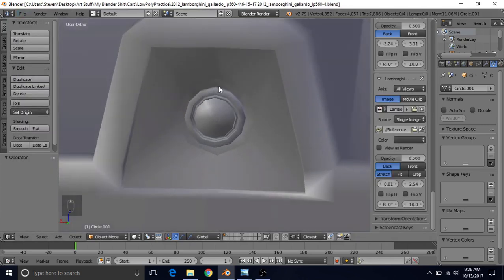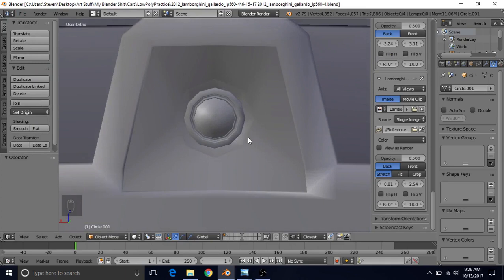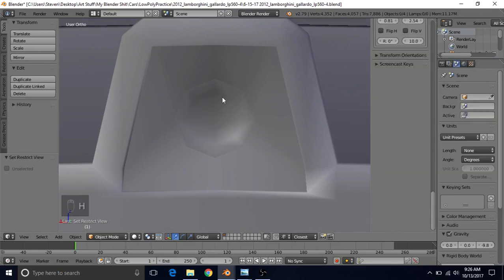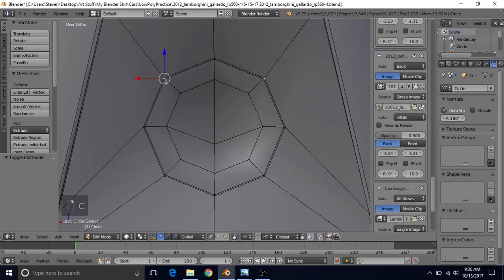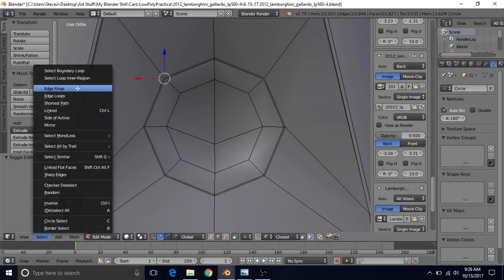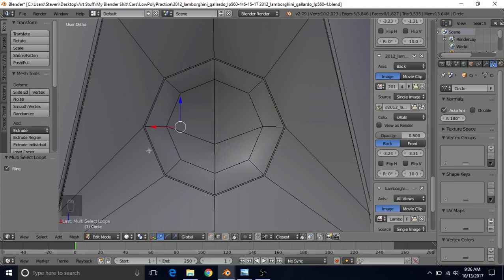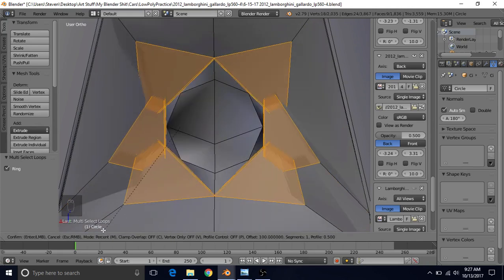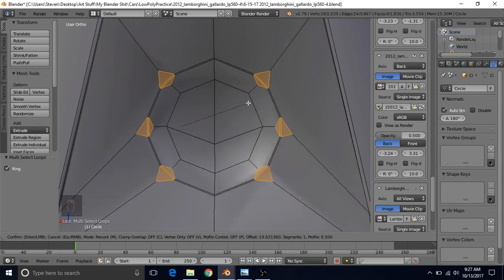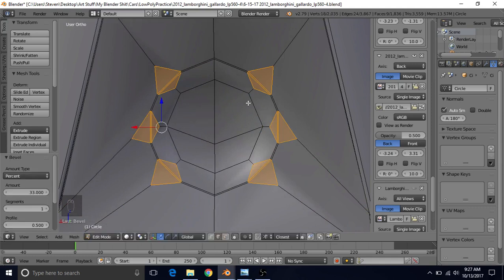To make this area here a little bit nicer, to make this a bit more round, we're just going to first select this in object mode and H to hide it so it's not in the way. Then select the car again, press Tab. We want to select these two vertices here. Go to Edge Select, do Select, Ring. That will get all the vertices there. Then do Control B. Then we're going to press M 3 times until down here it says percent. Should say percent right here. And we just type in 33 and press Enter.